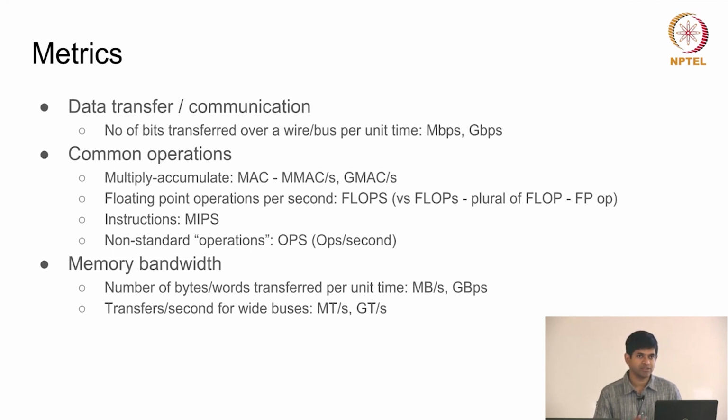So usually what happens is you have one register, you can think of it as a variable, which has some data that has already been accumulated over time. You have two other values, usually something like an input sample and a weight or a coefficient. You multiply those two together and add them to whatever was already present in the register. That operation is called a multiply accumulate, right? And is one of the most common operations in the domain of signal processing.